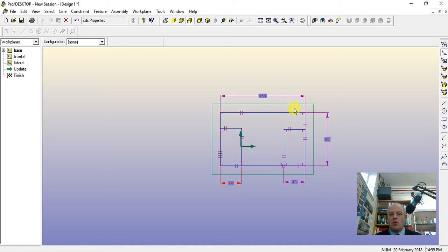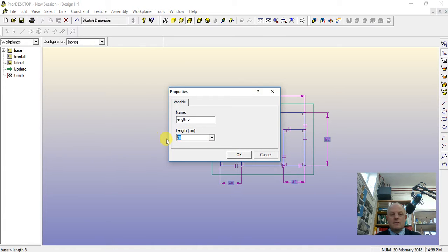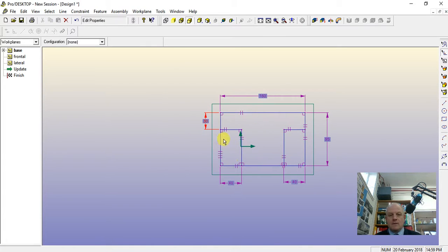I want that top part to be 30 millimeters. I haven't checked yet, so let's see what that is. Hover on the top line, hover on the step down height, keep your finger down, drag outwards, comes in at 28, pretty close. So double click, see if you can make that 30. So that one's dropped down a fraction. I haven't checked this side yet, so now I'm really dimensioning the whole thing. Top, hover on that line there, keep your finger down, drag it out. It is already 30, so I'm lucky that one's right.